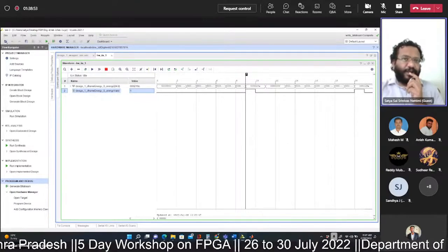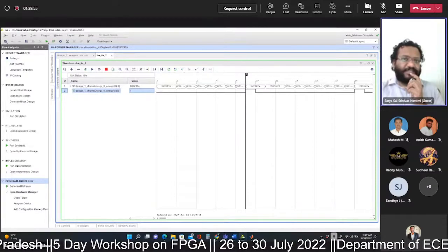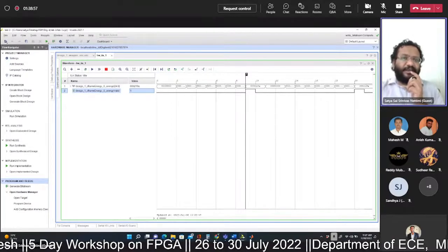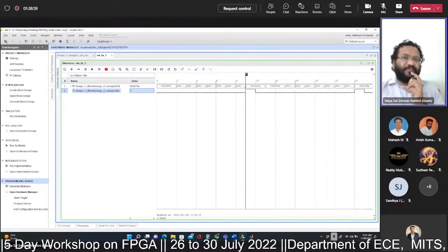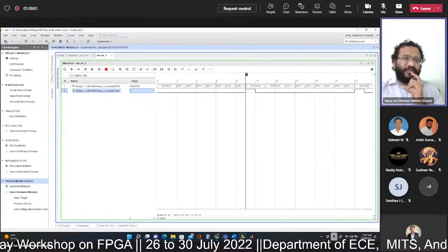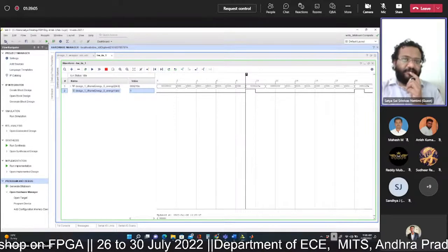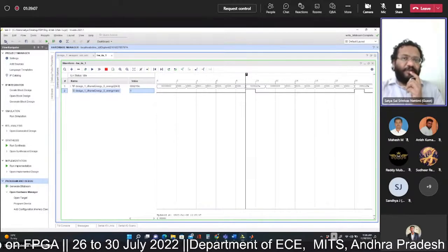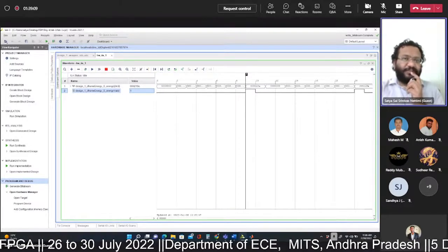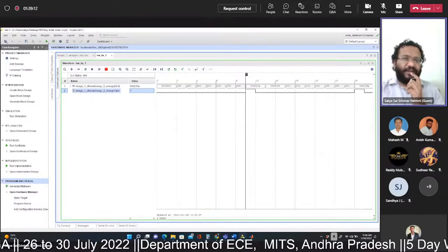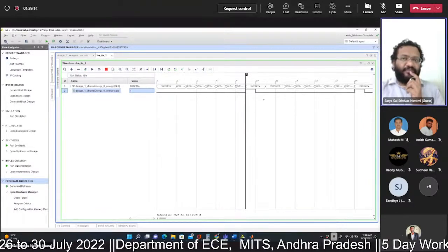That signal will be broken into frames. Each frame has a finite number of samples, and in speech signal analysis there is one parameter called frame energy. To calculate the energy of a particular frame, we take the frame, square all the samples within the frame, and then do a running sum to calculate the energy value.